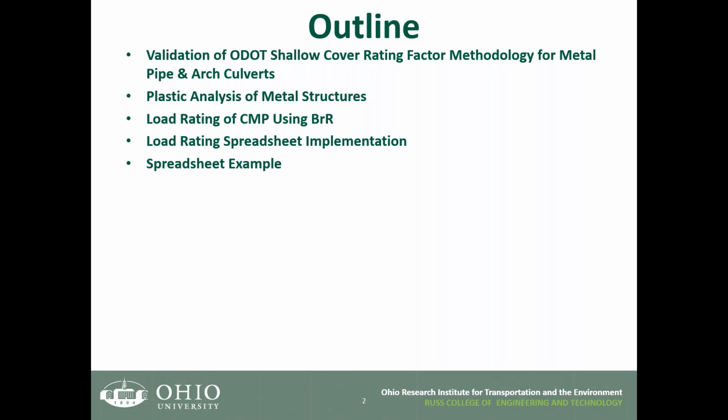The only time you will get in trouble with the pipe, and Kevin probably agrees with me from our many years of experience, is if you have a problem with the backfill material. If you lose the backfill material or something goes wrong with it, there is trouble. As long as your backfill materials are stable and strong, you don't have any problem. The pipe could carry a lot of load.